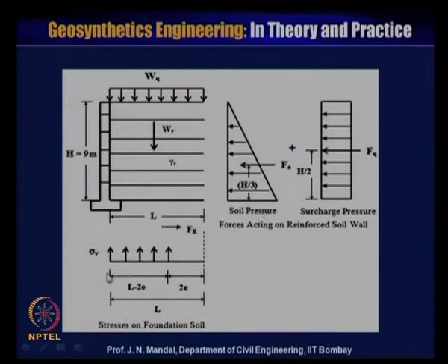So foundation soil may be very poor, so you want to improve the foundation soil. If you wanted to improve the foundation soil, there are various systems we will cover during our geosynthetics mechanically stabilized reinforced soil wall, but we have to determine what the stresses on the foundation soil should be. So we will adopt this Meyerhof pressure distribution.